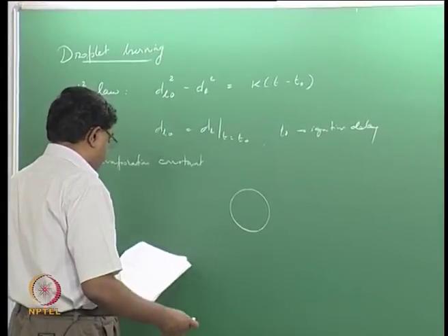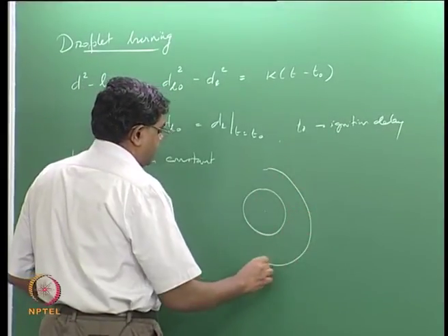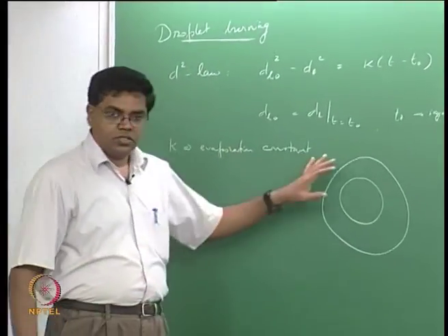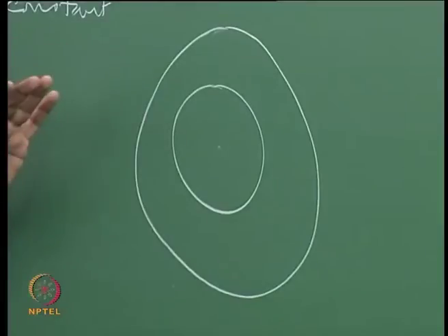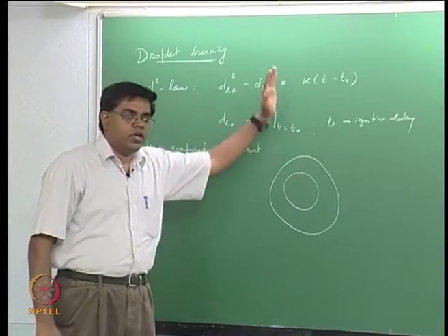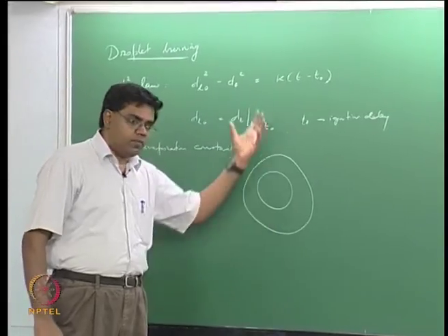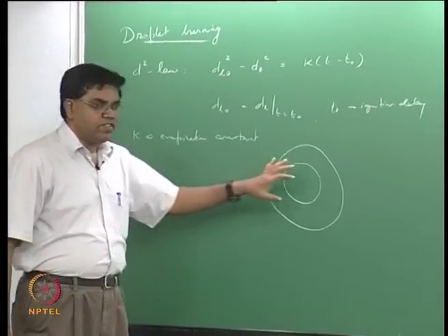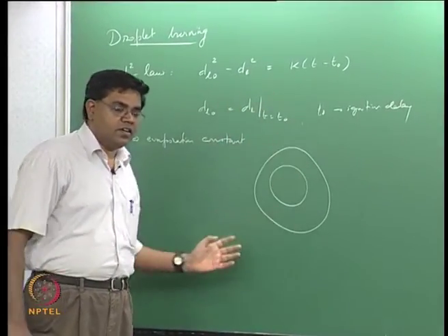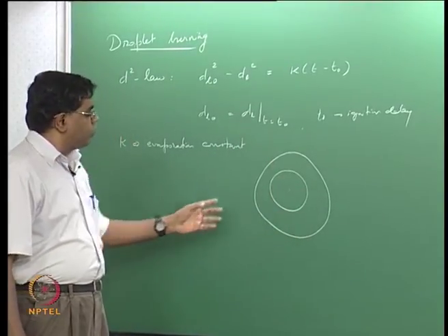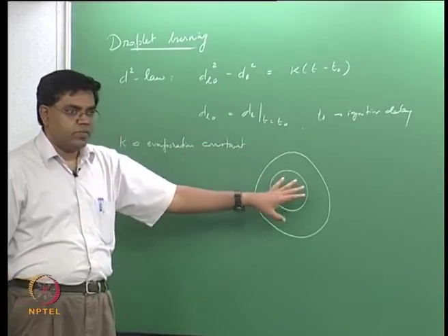And then this is the fuel, and what we expect is that there must be a concentric flame around it. Now this is a questionable assumption in a gravitational field, because buoyancy effects will induce a vertical convection upward and also distort the flame shape in a way that is pointed upwards. And of course what we are looking at is a droplet stationary in a quiescent gaseous oxidizing ambience. Therefore we could now assume the spherical flame concentric to the droplet.